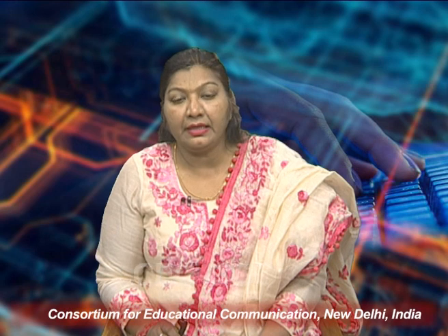Another type of fuse is the high voltage fuse, and it is used in the power system to protect the power transformer, distribution transformer and instrument transformer, etc. Where circuit breakers may not be able to protect the system, high voltage fuses are rated for more than 1500 volts up to 13 kilovolts. The element of the high voltage fuse is generally made of copper, silver and tin.